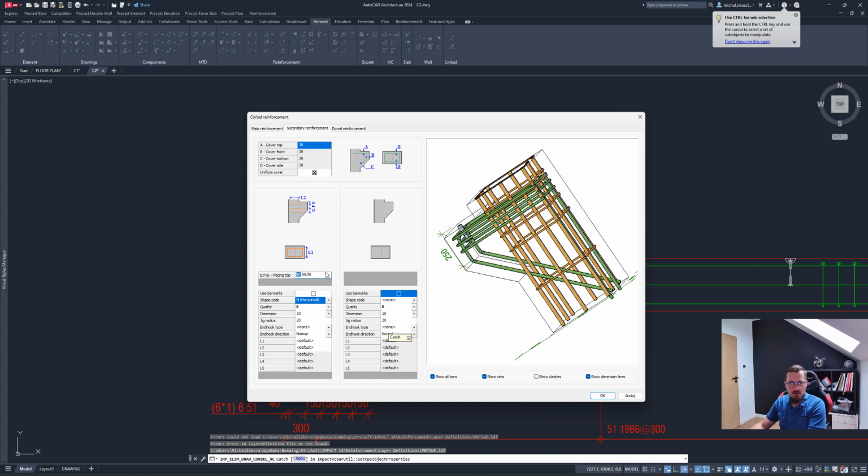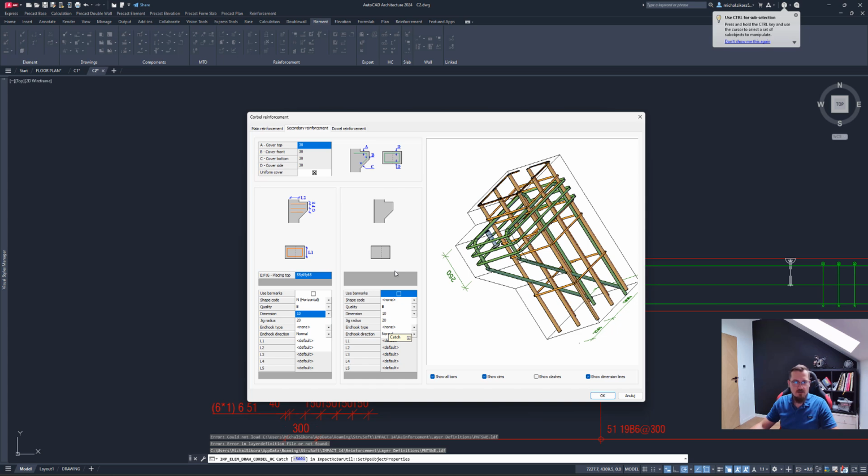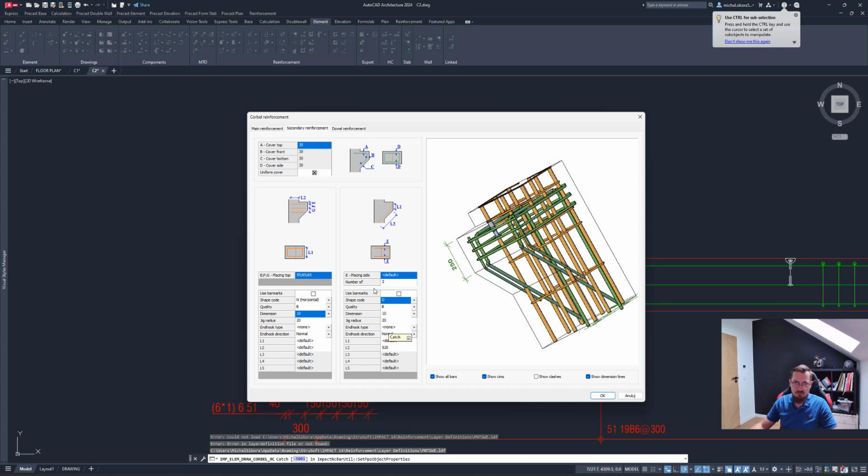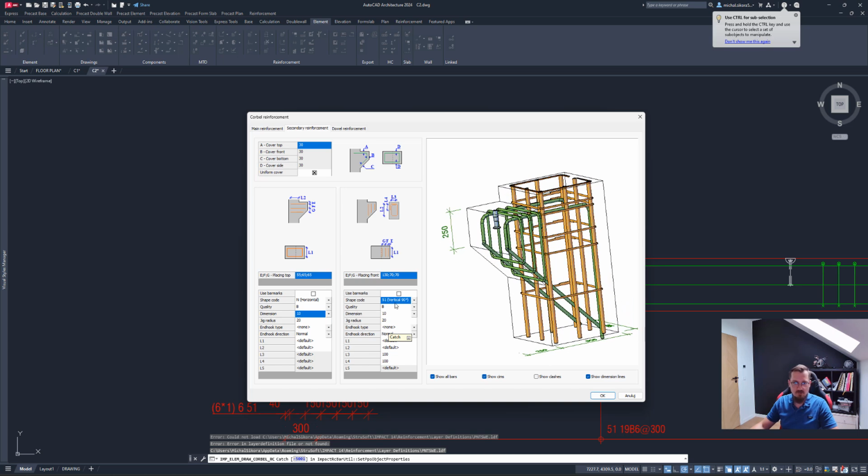So let's change that to maybe 55 on the first dimension. Right, that moves down, and let's maybe go 65. Oops, 55. Let's go 65 and 65. Yep, that looks better to me. So we can leave it like this. And for the other reinforcement, of course, there are multiple ways you can add that Corbel reinforcement. As you can see right now, there's really a bunch of reinforcement. If we want stirrups going this way, sure, you can do that as well.